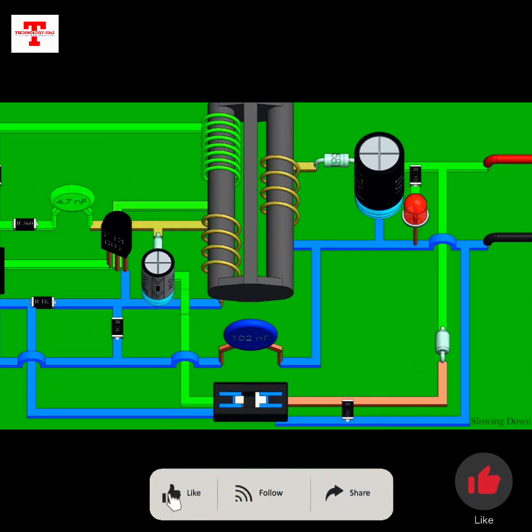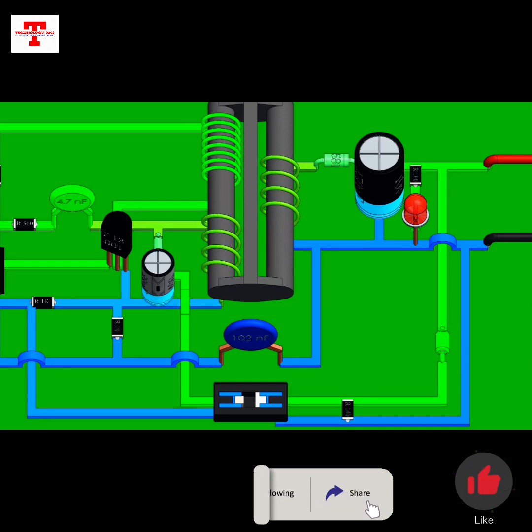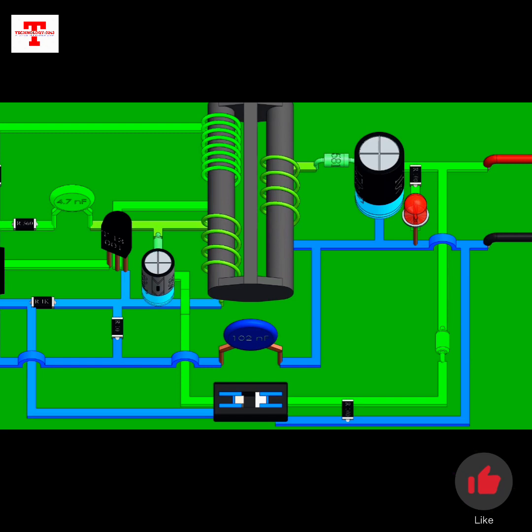As we reach 4.2 volts, the Zener diode turns on, allowing current to flow to the optocoupler. It also drops the voltage by 4.2 volts, hence the LED of the optocoupler doesn't turn on. The LED requires 0.8 volt to turn on. When the voltage reaches more than 5 volts, this turns on the LED of the optocoupler. The light of the LED turns on the phototransistor of the optocoupler, allowing the current to flow to the transistor T2. This turns on the transistor T2, shunting the first and stopping the flow of current in the primary winding. Also, the voltage on the secondary side of the transformer drops below 5 volts, turning off the Zener diode and optocoupler, and the circuit continues to run normally.